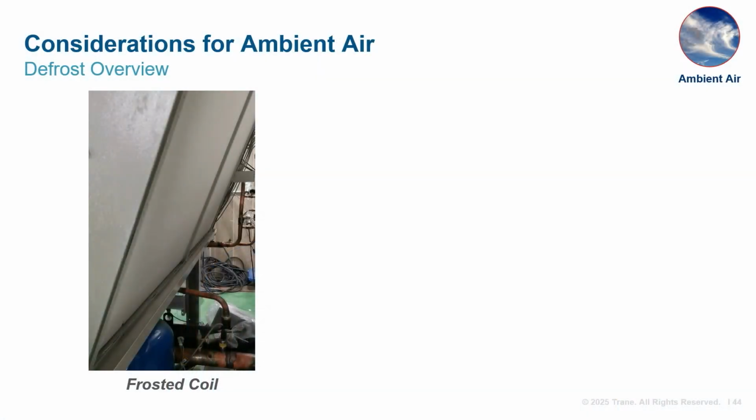When air-to-water heat pumps operate in an ambient temperature of 47 degrees or lower, the coil surface temperature may be at or below freezing temperature. Humidity in the air can collect and freeze on the coil surface, causing a layer of frost and degrading the coil performance. When visualizing defrost, think about a thin layer of frost, like frost on a window. Images of heat pumps covered in snow and ice are not a good representation of defrost operation.